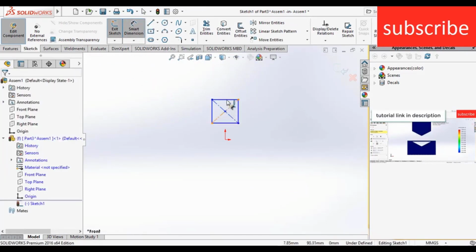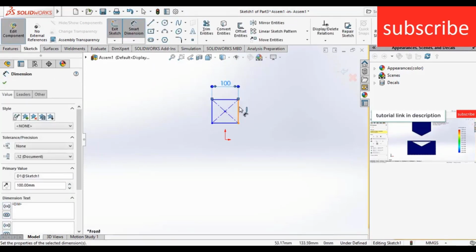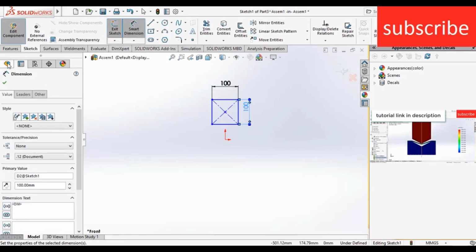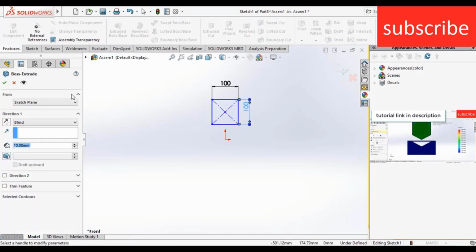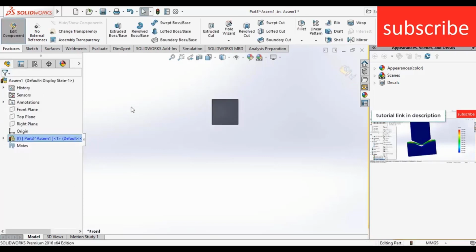Now enter the length or breadth as per your requirement. Here I am making a square of 100 by 100 mm and going to extrude it up to a length of 100 mm. Make sure you select mid plane because it will make it easy for us while doing simulation.